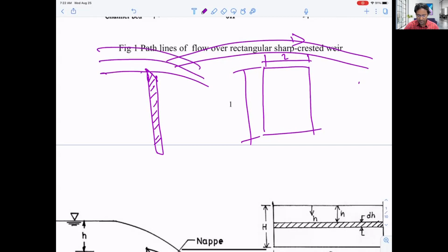So we are just making this tip of the weir sharp in order to toss the water, right, with this weir to a line. What if water flows over this weir, and we make this tip sharp, like a blade, so water will touch as a line? Then the interaction between water particles and this weir will be minimum, and our frictional loss will be minimum as well. So in order to do that, we'll use a sharp-crested weir.